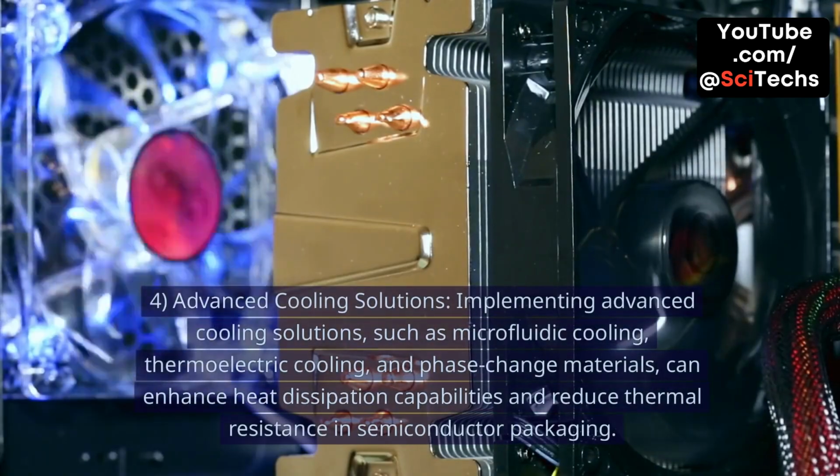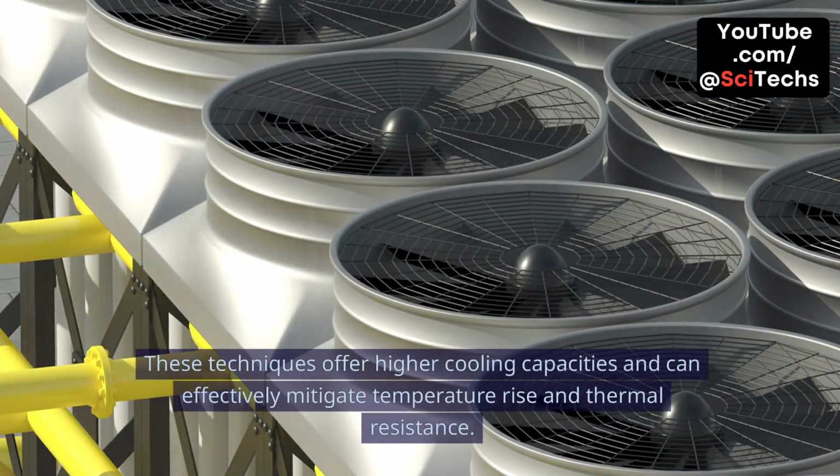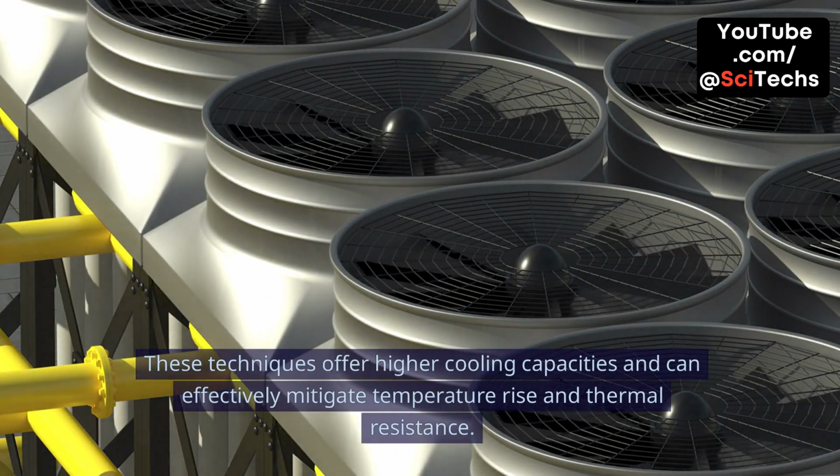4. Advanced cooling solutions. Implementing advanced cooling solutions, such as microfluidic cooling, thermoelectric cooling, and phase change materials, can enhance heat dissipation capabilities and reduce thermal resistance in semiconductor packaging. These techniques offer higher cooling capacities and can effectively mitigate temperature rise and thermal resistance.